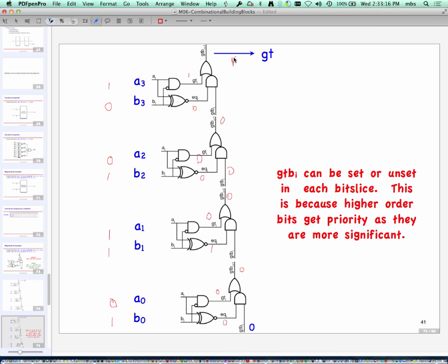Now when it comes to, let's say, a 3 input XOR gate, then the definition is actually a little bit tricky. Generally speaking, if I have an n input XOR gate, some people say that the n input XOR gate means an odd number of inputs are 1. Okay. Some people say that an n input XOR gate means only one input is 1.